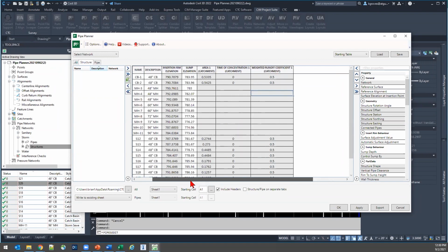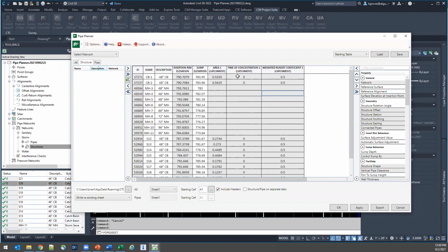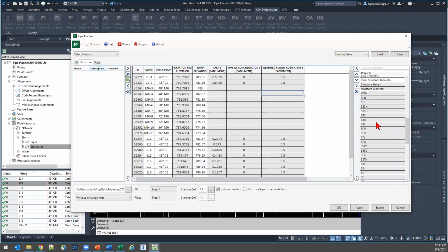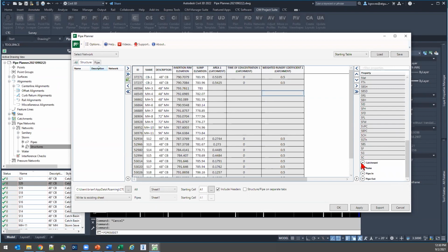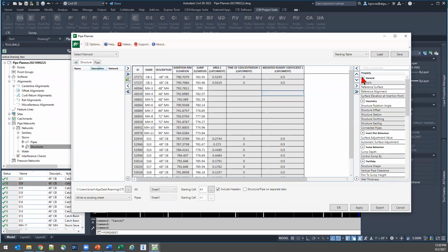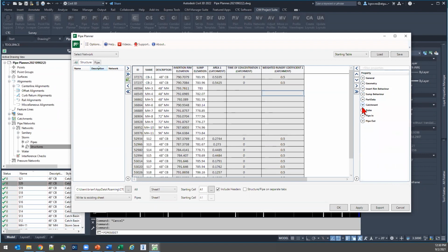So this is how we're getting the power to create those tables that we can then spit out and work with our hydrology stuff. Because we've got those catchment areas, we can even do our runoff coefficients. Now we can really start playing around with how much water this structure is going to take, how much is going to get passed on to that pipe downstream of it. Are these pipes big enough, steep enough, etc. So you'll find that in here. I'm not going to go through all of these different pieces of data. Just suffice it to say that if we can find it in the API, then you can read it here in this list. And if it's in this list, you can add it to your stuff. So all these different categories worth of data.